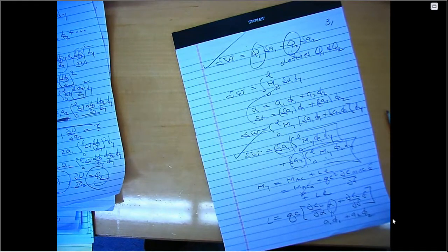And the number of equations will be equal to the number of terms you retain in the series for alpha. Okay? And in general, those equations will be coupled. That is, in the equation for the A1 equations, well, A2 and A3 and A4 will appear. For the special case where GJ is a constant, I think the equations may prove to be uncoupled. They certainly won't be uncoupled when GJ is not a constant.